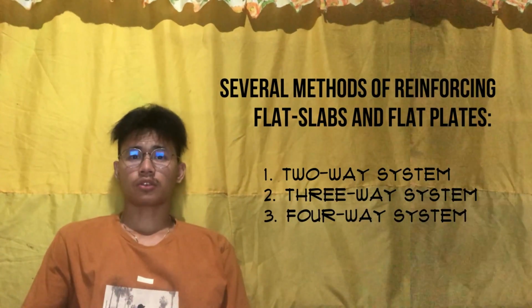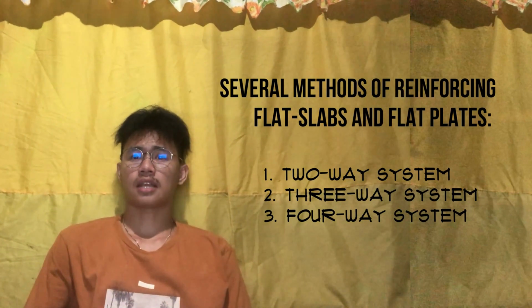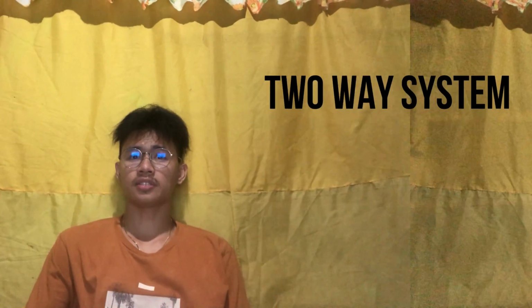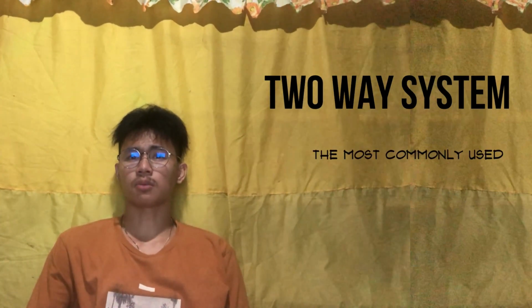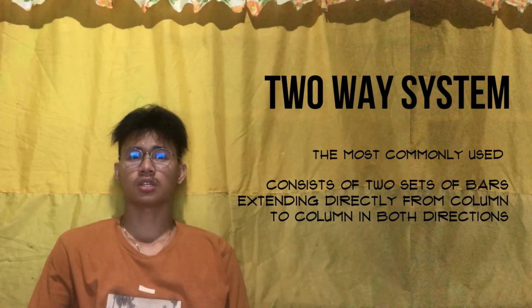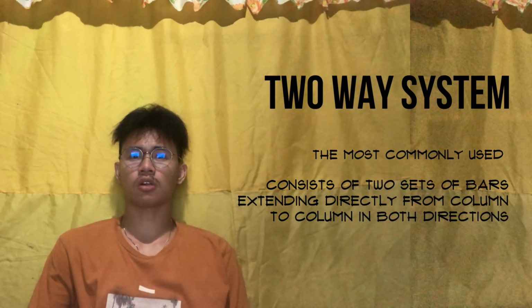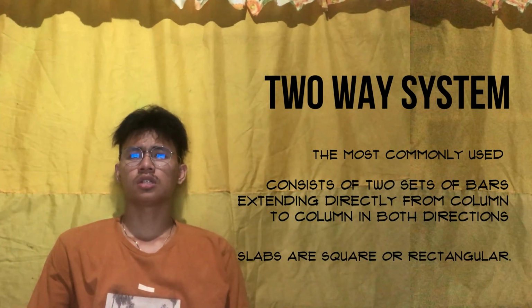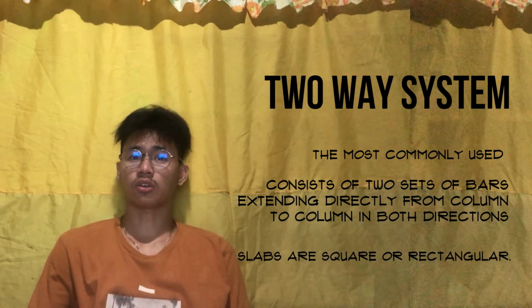There are several methods of reinforcing flat slabs and flat plates. Number 1. Two-way system. This system is the most commonly used and consists of two sets of bars extending directly from column to column in both directions. Slabs are square or rectangular.